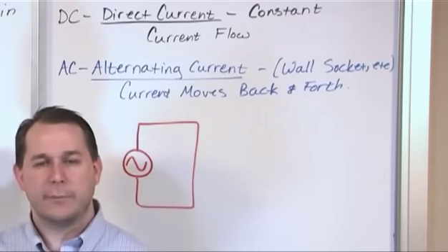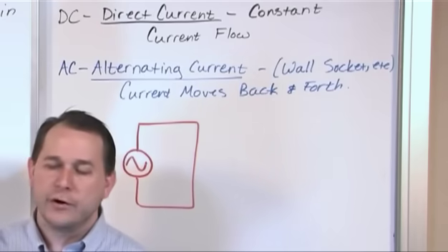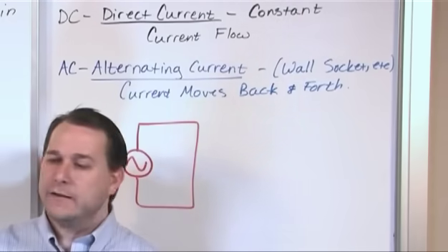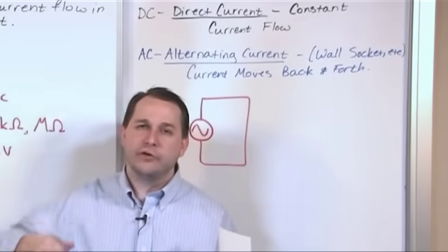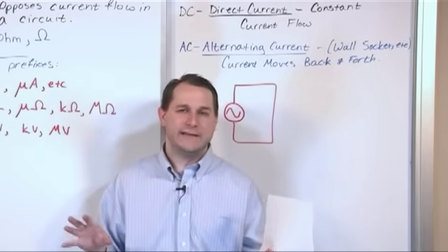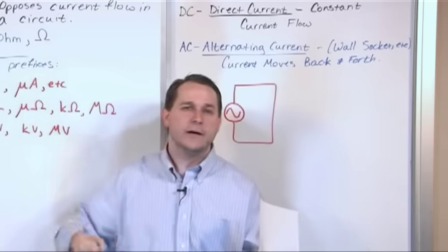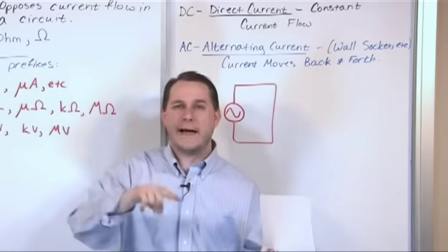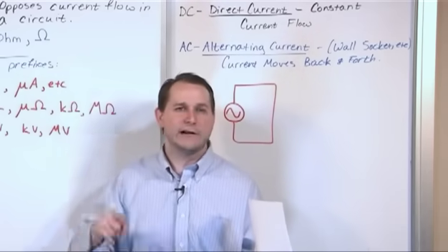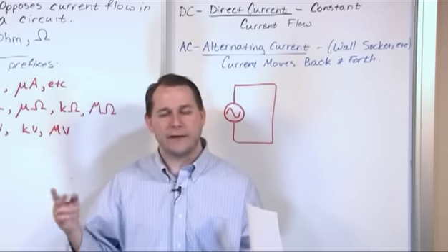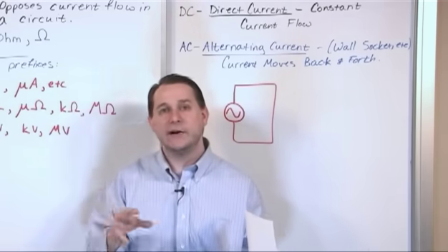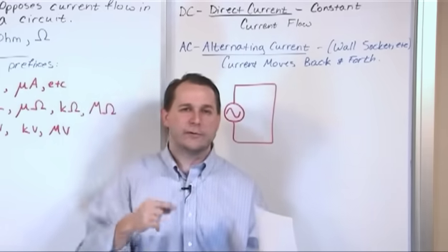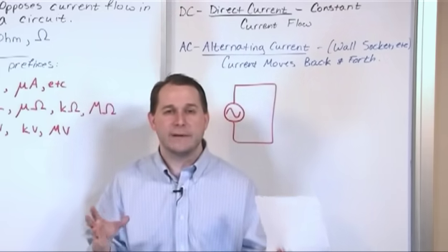Really, all of our power plants, whether they're gas or nuclear or coal, all they do is generate a lot of heat, and that heat usually heats up steam, and that steam turns a generator. So all of our power plants, even the wind farms, are just turning a generator. Every time we generate electricity, except with solar panels, we do it by rotating a wire inside a magnetic field, which is what's inside a generator. That rotation is a direct result of how we get alternating current, and that's the reason power plants do that.